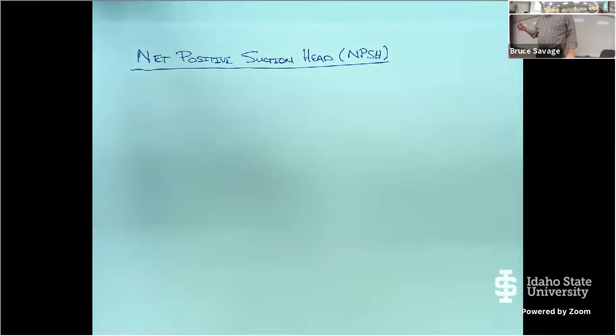Cavitation is the rapid change of a fluid, and I guess we have to be a liquid, from the liquid phase to the gas phase. All right. So cavitation forms little gas pockets, and I think we may have talked about this a little bit, but I'll review it. So it's not an air bubble. I have to be a little careful with my terminology. So if we're going with water, it forms water vapor, just like when you're boiling water. It's water vapor, and that water vapor is in a bubble, and as the pressure continues to go more negative, that bubble grows and grows and grows.